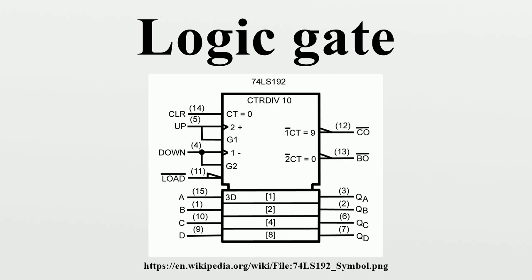Logic gates are primarily implemented using diodes or transistors acting as electronic switches, but can also be constructed using vacuum tubes, electromagnetic relays, fluidic logic, pneumatic logic, optics, molecules, or even mechanical elements. With amplification, logic gates can be cascaded in the same way that Boolean functions can be composed, allowing the construction of a physical model of all of Boolean logic, and therefore, all of the algorithms and mathematics that can be